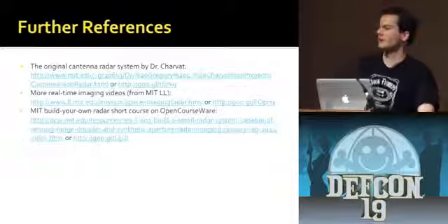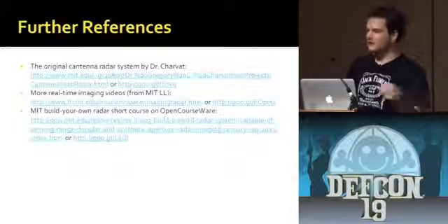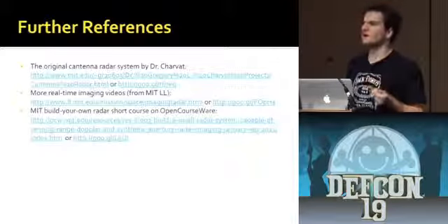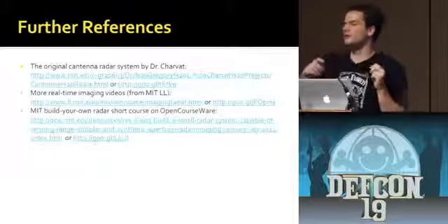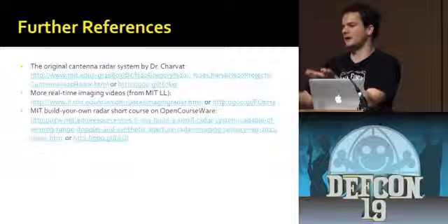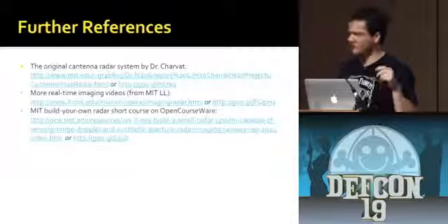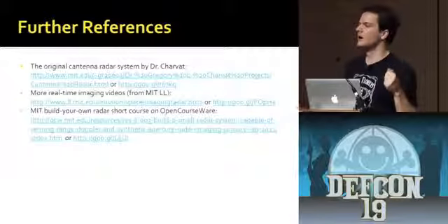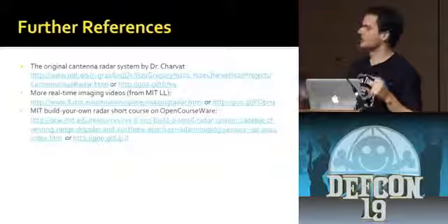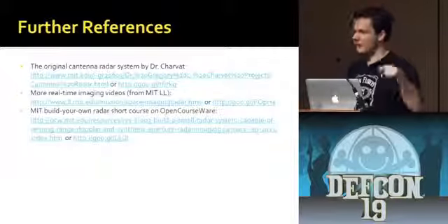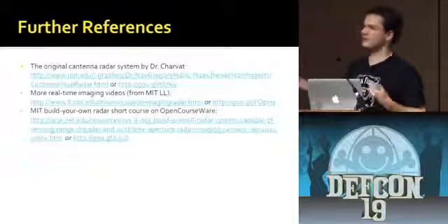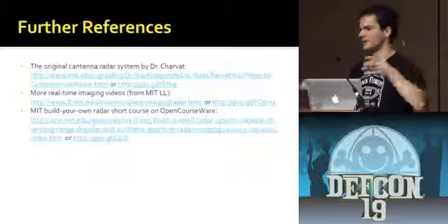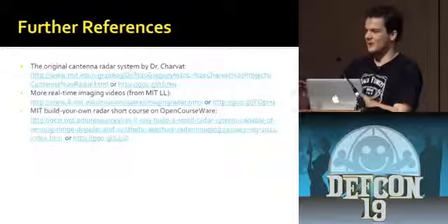He asked, is the Doppler effect from a fast-moving object enough to mess up your position measurement? That kind of depends on what you're trying to do. If you're trying to measure something moving really fast, on the order of a plane, you might have some impact. When I was talking about it before, I said that something moving 3 meters per second, like a person walking really quickly or a slow jog, produces a 24 hertz signal. At the chirp rates I was dealing with, I think 10 meters corresponded to 667 hertz. So it wouldn't affect it too much, but that all depends on your chirp rate and your bandwidth and a bunch of other factors. You could make it have an impact or not.